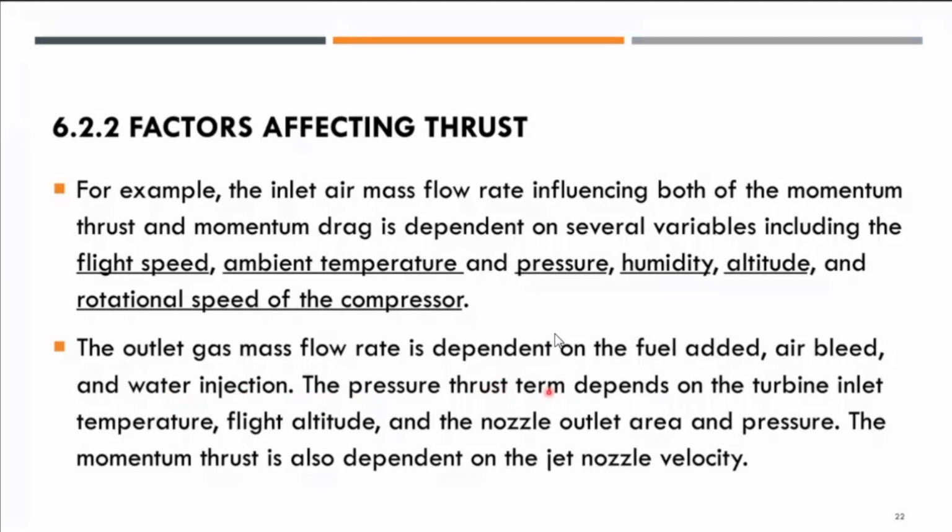The pressure thrust term depends on the turbine inlet temperature, the flight altitude, how high or how low the aircraft is flying, as well as the nozzle outlet area and pressure. And the momentum thrust is also dependent on the jet nozzle velocity. So we will look into this one by one.